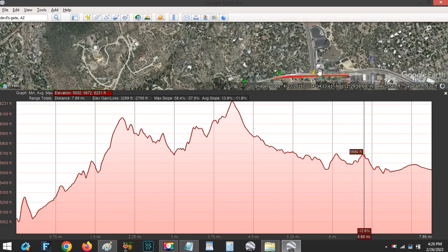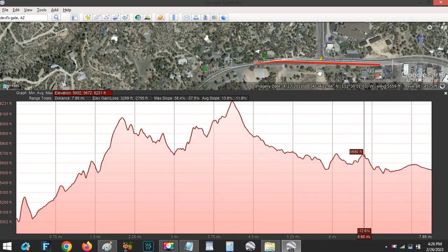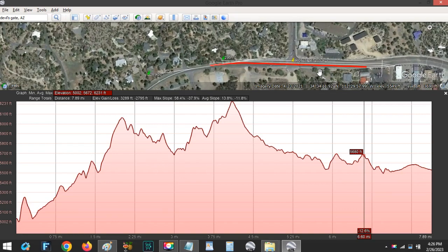At this big hump that the road apparently goes over such a hump. Now we're on the other side, so at about the height of that hump, there it is on this curve, and here's where it comes and splits. So you don't want any vertical curve where the switch is.